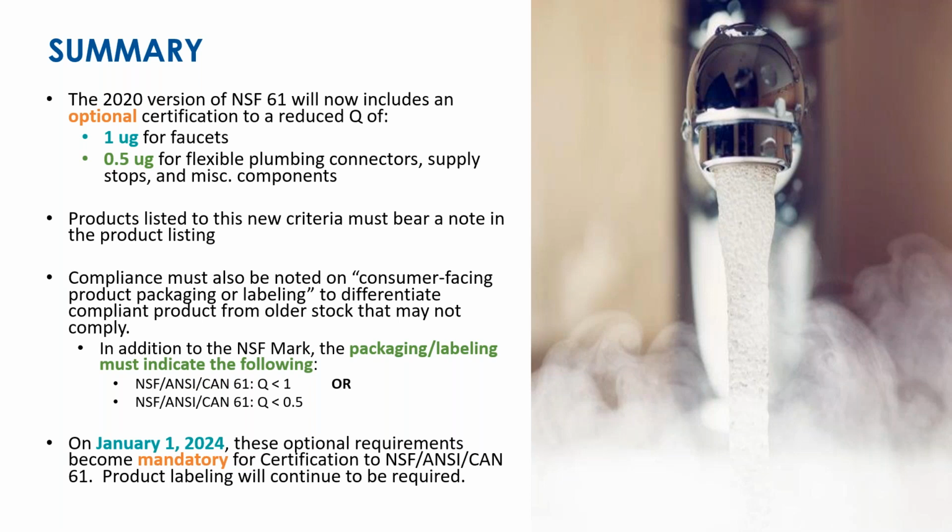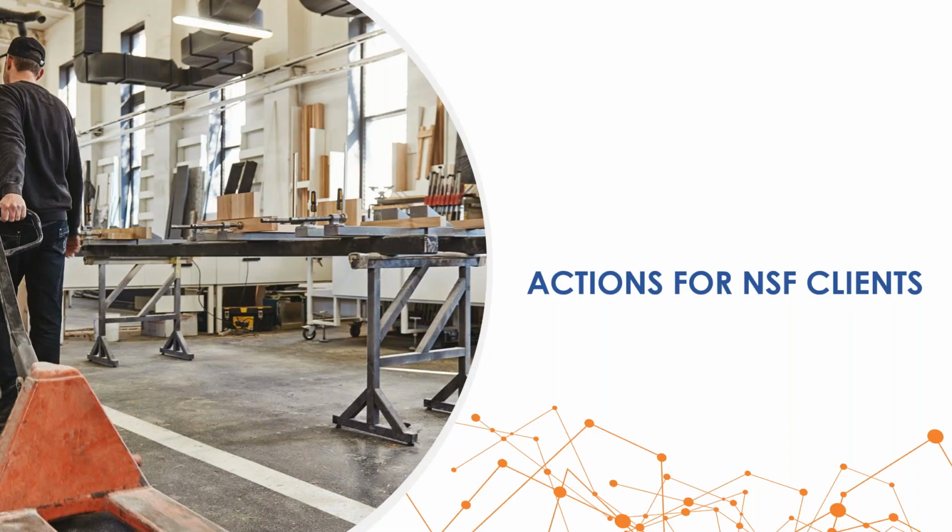Then on January 1st of 2024, these optional requirements become mandatory for certification to NSF 61, and all faucets must be demonstrated to meet those criteria in order to stay certified to Standard 61. The product labeling requirements will continue to be required even past that January 1st, 2024 date. So if you are a currently certified NSF client and you make these endpoint devices that are present in the last liter of drinking water, that's certified to Section 9, what should you do next?